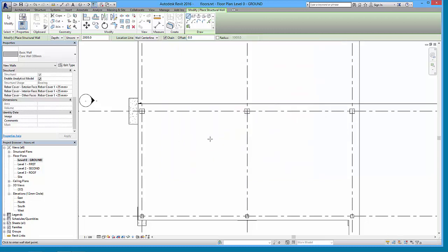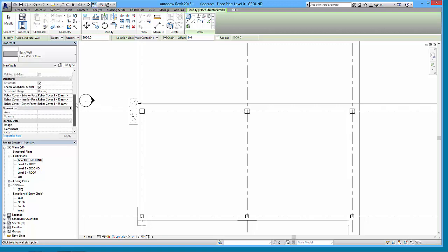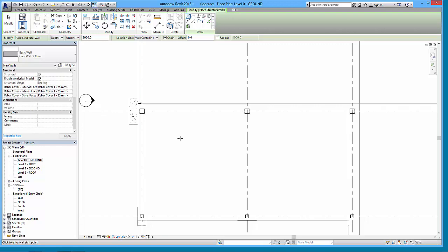So that's all that's done to this point, is set our family type, which is a system wall. The type of it is now a core wall, 300mm, made up of concrete. And again, we've got structural usage, bearing, rebar cover, blah blah blah. We're going down, so this is stuff that other people can sort of pick up and develop.